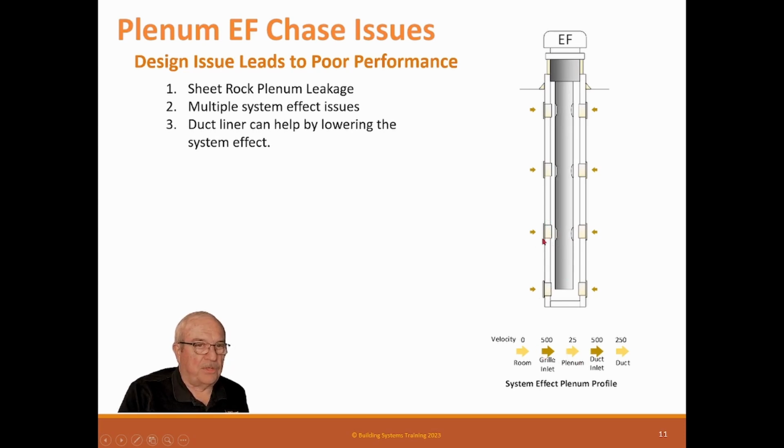It'll get rid of those pressures. This doesn't look good, but it has to be close. The inlets have to be 3 or 4 inches away. They can't be 10 feet away or 5 feet away to make this work. But it will work. It's just a plenum down there with open holes for this 50 CFM coming from each side as long as they're close.